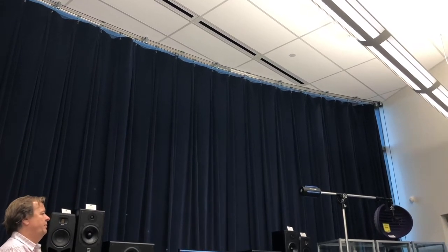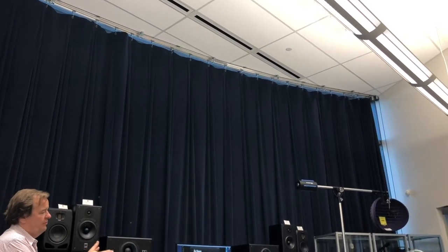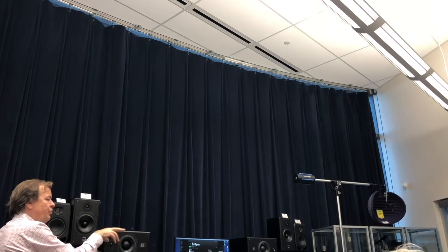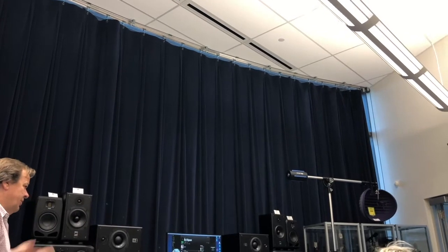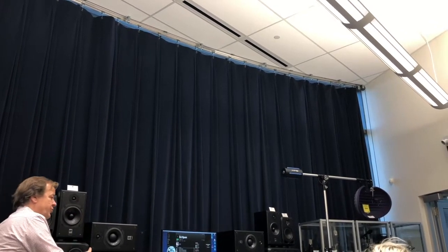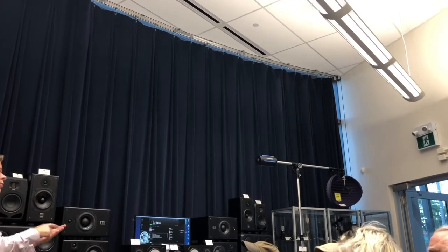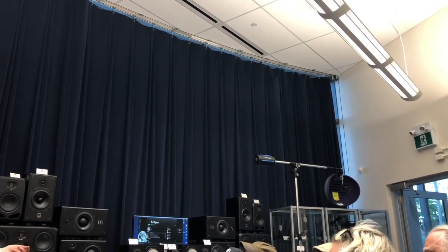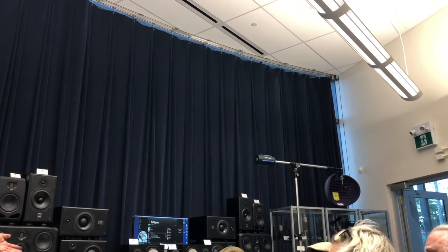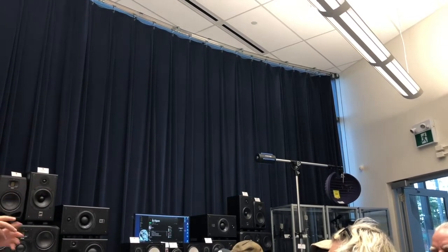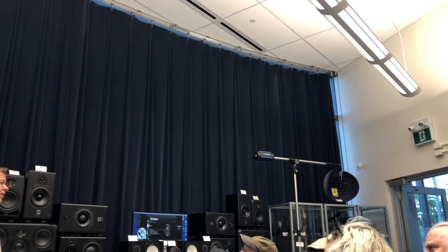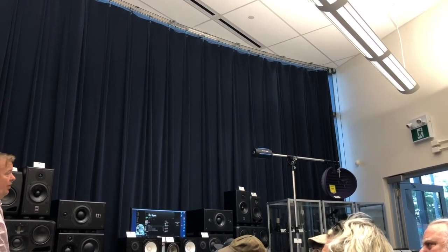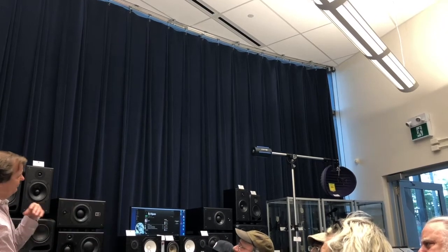Most of the time, if you need one GPIO because you have just a small device, take the example of a journalist doing a show outside somewhere with two microphones. He wants a red light and talkback with a pedal, and he doesn't care about MIDI because it's a small infrastructure. Then you put it into a bigger infrastructure where you want MIDI, for example, to remotely control some stuff. But then the GPIO would need more than one input and output, because you have several red lights and several things. Then you would have a device on your workstation via USB with relays able to switch on and off. But GPIO is a very old style of concept.